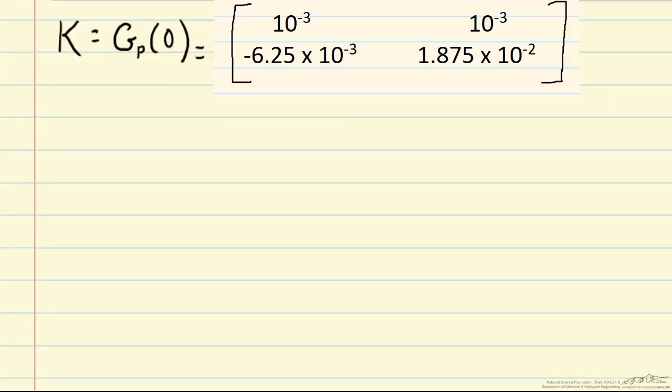In any case, the steady state gain matrix here tells us how an input of unit height will lead to a change in the output. So it's that proportionality constant, or our system gain. And by inspecting this gain matrix, we can actually figure out how we should pair up our two inputs and our two outputs. We can see from the first row that our two inputs, W1 and W2, equally affect the volume change in the tank. So those gains are equal, so it's not really clear which input we should pair with R.